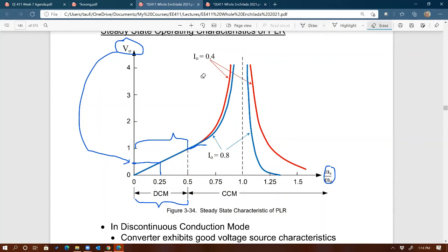Let's just do it this way. Change this to infinity, right? Let's just say that's for infinity. That means along this red line is going to be infinity current, yes? So at this point, don't you still have infinity current? Yes. Exactly. So your load is still seeing infinity. That's not going to protect it from short circuit current. The voltage, however, will still be the same voltage, but the load is still seeing huge current. That's not an advantage. Do you agree?